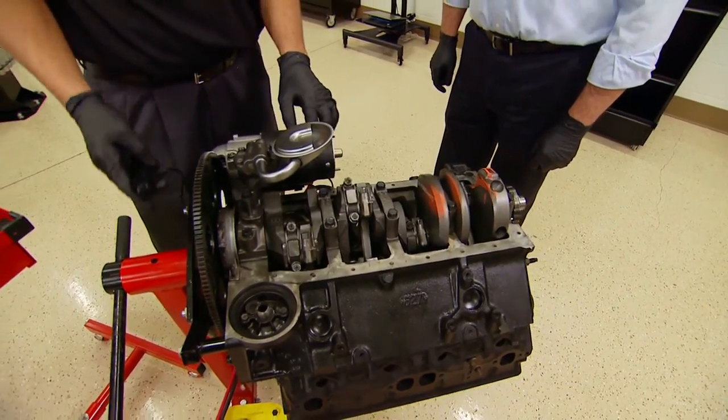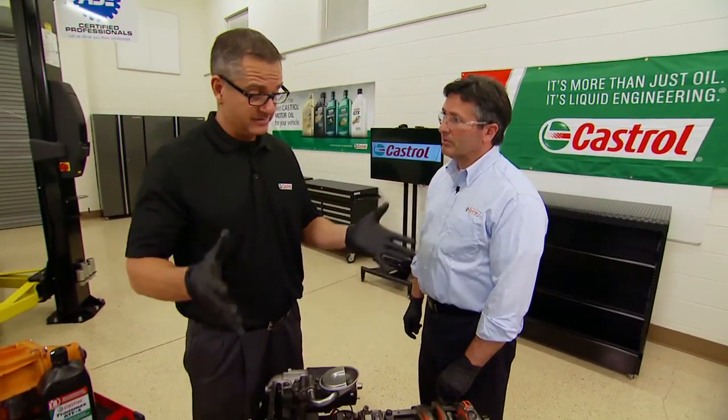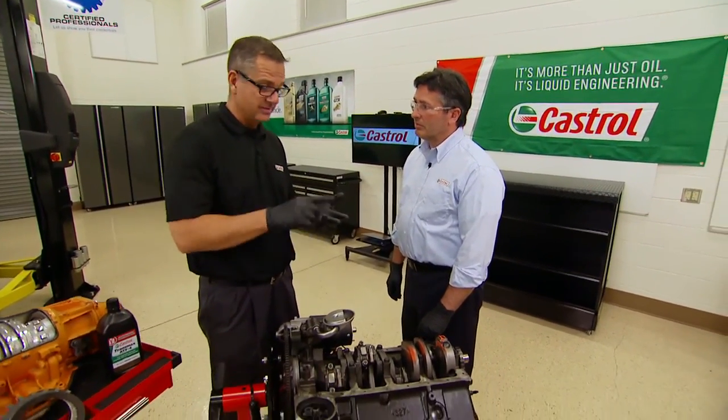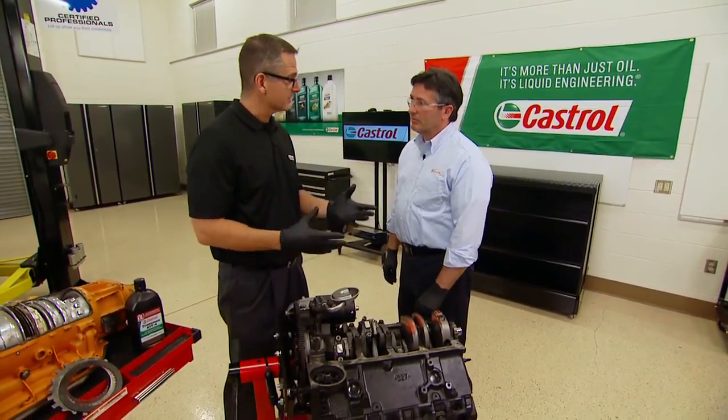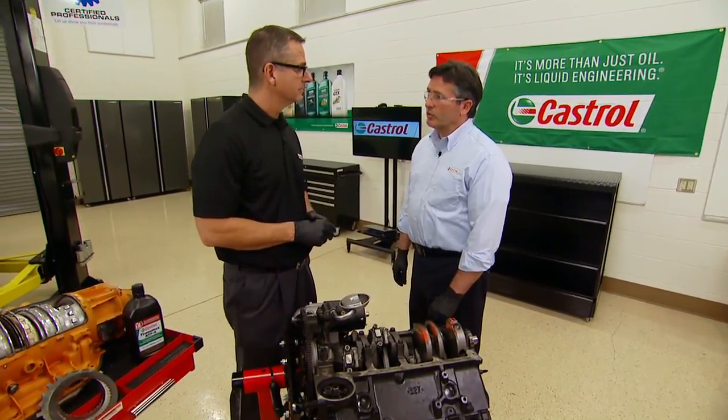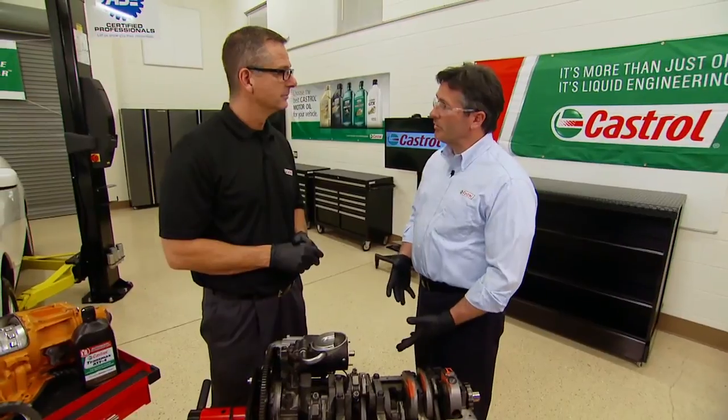That's going to whip that oil up and create a lot of air. Yes. Now one other one, corrosion inhibitors. The job of the corrosion inhibitor is to prevent rust formation from moisture that enters the inside of the engine. So really the additives, the anti-foam agents, dispersants, detergents, and everything we just talked about, that makes the oil package? Yeah, it's a critical choice between the types of engine oil additives and the performance of the engine oil additives that helps differentiate engine oils.